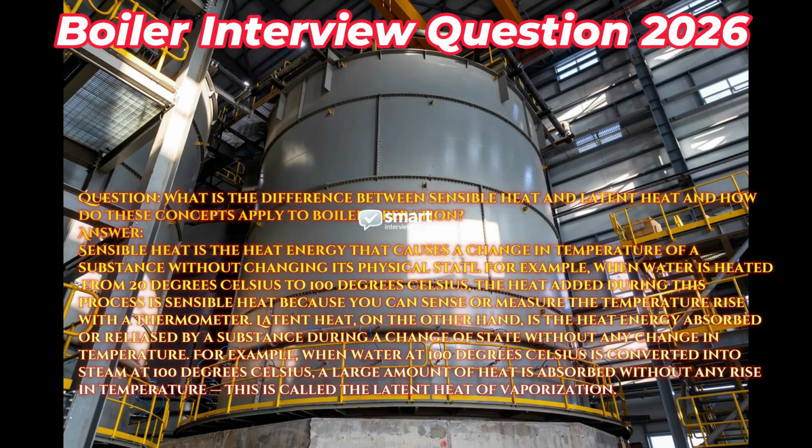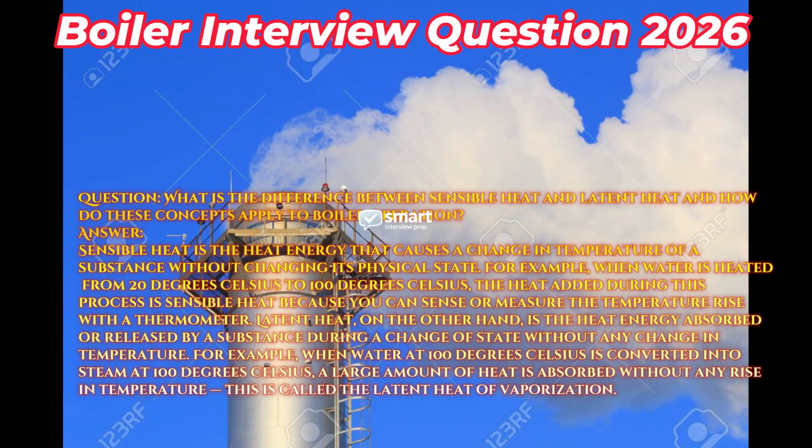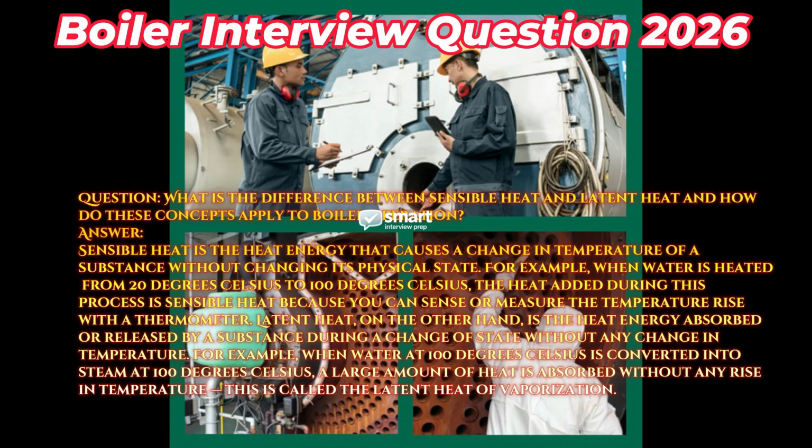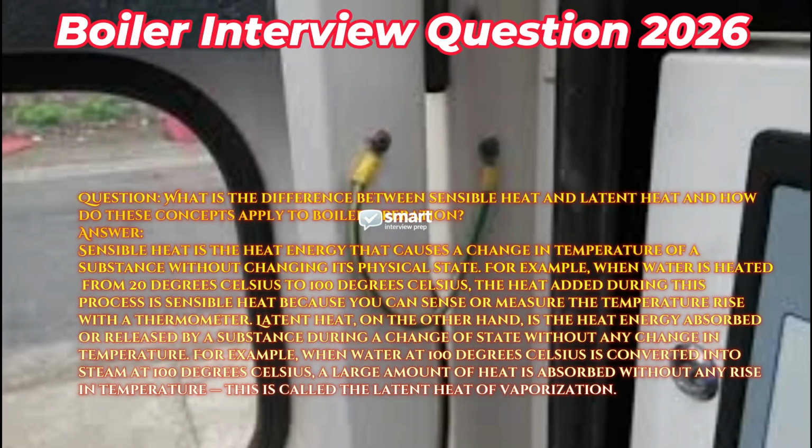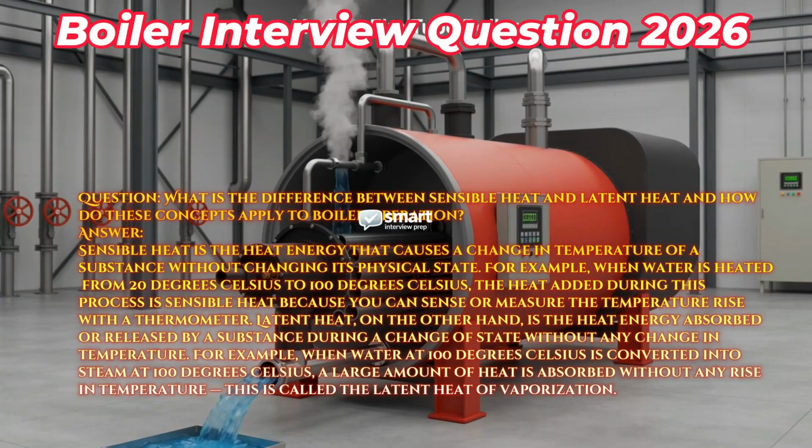Question. What is the difference between sensible heat and latent heat, and how do these concepts apply to boiler operation? Answer. Sensible heat is the heat energy that causes a change in temperature of a substance without changing its physical state. For example, when water is heated from 20 degrees Celsius to 100 degrees Celsius, the heat added during this process is sensible heat because you can sense or measure the temperature rise with a thermometer.